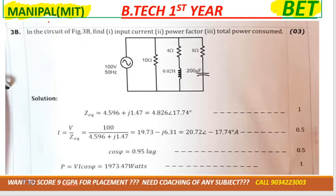see this is a question from your question paper, the NTEM question paper. In this they have given a simple circuit, and as you can see this one is a parallel circuit, right? So the very first mistake which students generally, Manipal students, make is they don't see that it's Henry, they'll feel like 4 plus j 0.02. No, you have to see the units. It's 4 ohm, that is a resistor. It's 0.02 Henry, right? Now tell me, is it L or XL?